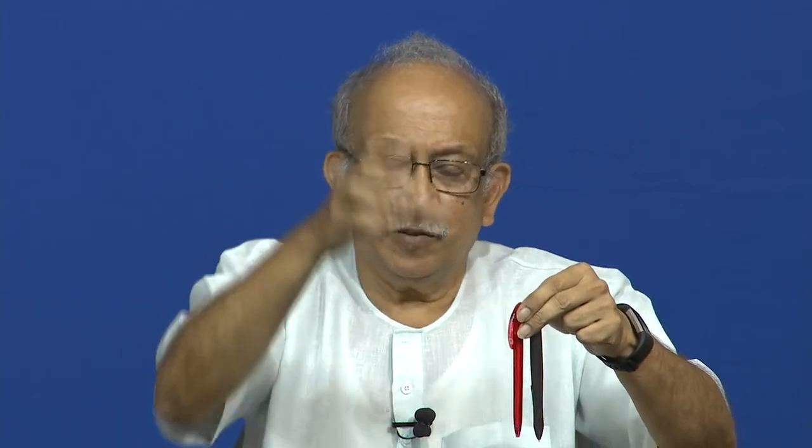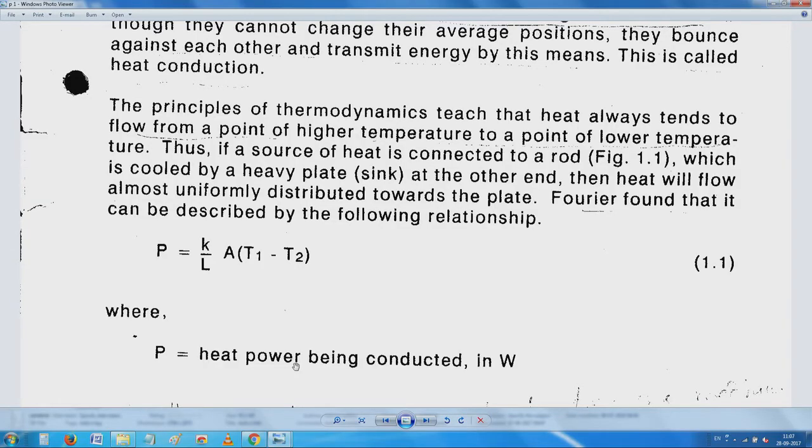Now comes the interesting experiment. If you fill it with hot water after the wax is set, the one which has the highest conductivity, in this case let me say this is copper, the slider slides very fast almost all the way to the bottom, because the teacher would have done the experiment earlier. The one which has slightly lower conductivity only comes halfway. The one which is not a conductor stays on the top, which is a good starting point for us to understand that the length of conduction also is important, how far away the conduction is.